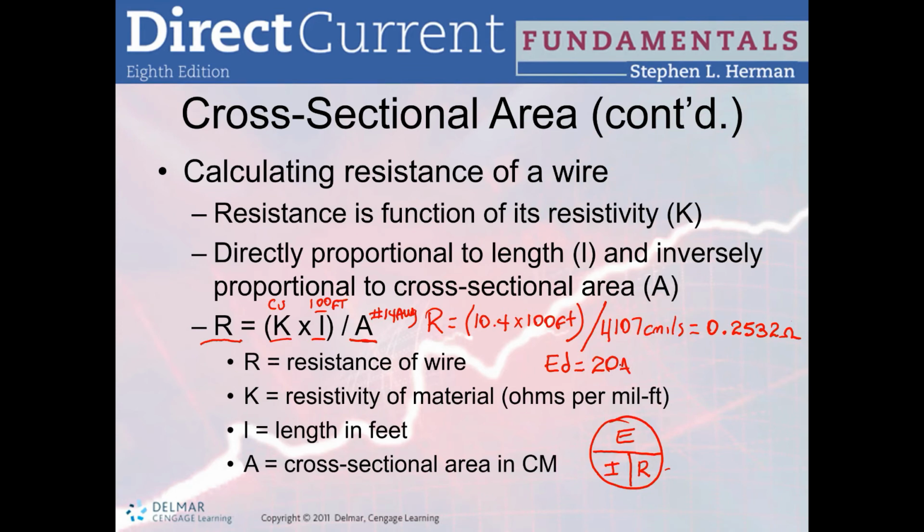I know you might be saying, wait a second, you cannot put 20 amps on a number 14 conductor, but Table 1 in the code book at 90 Celsius actually says that you can. You can even put 25 amps, no problem.